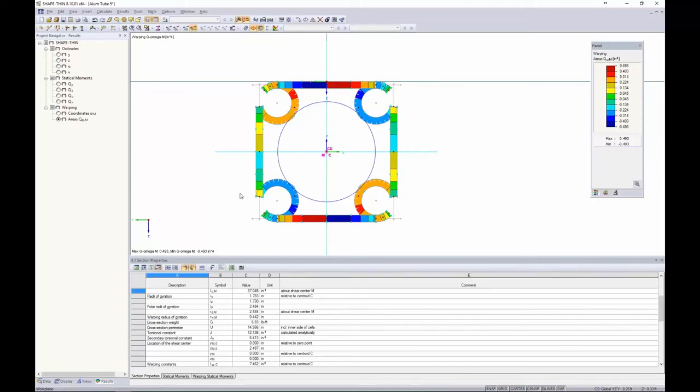And that's because I need to implement these C sub T elements within Shape-Thin. And C sub T elements are just width to thickness ratios. Now, in order to implement C sub T elements, they can only be added to these straight line segments here. They cannot be added to these arcs. So if I was concerned with local buckling of one of these arcs, or had some other different shape where I had a rather large arc that I'd like to check local buckling, then it's suggested that you create multiple straight lines that compose those arc, and then you can create the C sub T elements.